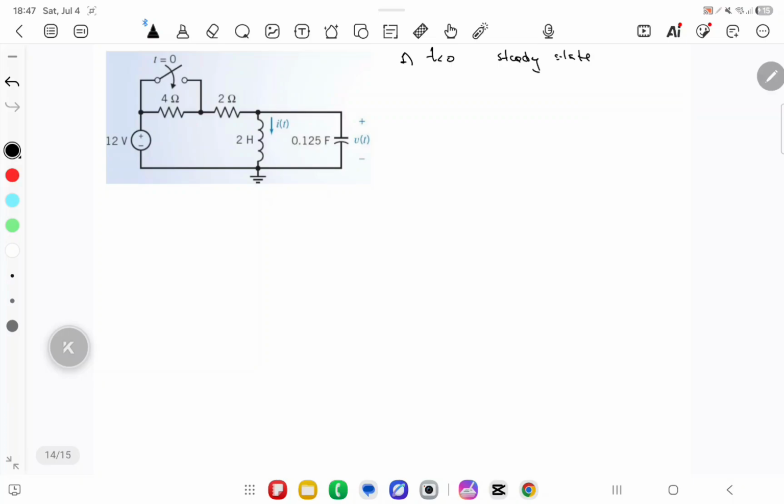our inductance and capacitance, because our voltage across the inductor, for example, is equal to L multiplied by di/dt. But as we know, the DC current does not change, so this is essentially equal to zero. The same goes for the current across the capacitor. Our current is equal to C multiplied by dV/dt, and our voltage in the steady state is steady, so there is no change in voltage, and this is equal to zero as well.